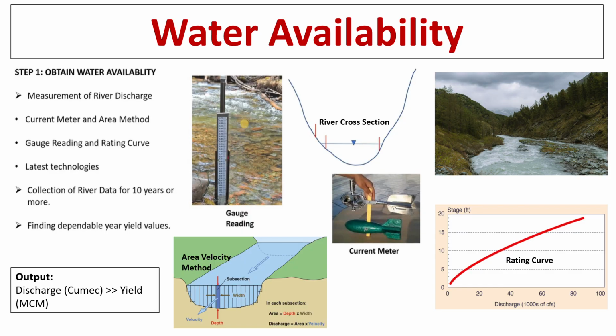The concept here is measuring velocity and multiplying it with the area of the river section. If we take one velocity reading and multiply with the area of the river section, it will be rough and it may not give an accurate discharge value, since the river section varies and also velocity varies. Velocity is different at the banks and different at middle portions. In this regard, as shown in the image, the river is divided into segments. Velocity is measured in each segment using a current meter. Once the velocity is obtained, multiplying with the area of each segment and adding will give the discharge value.